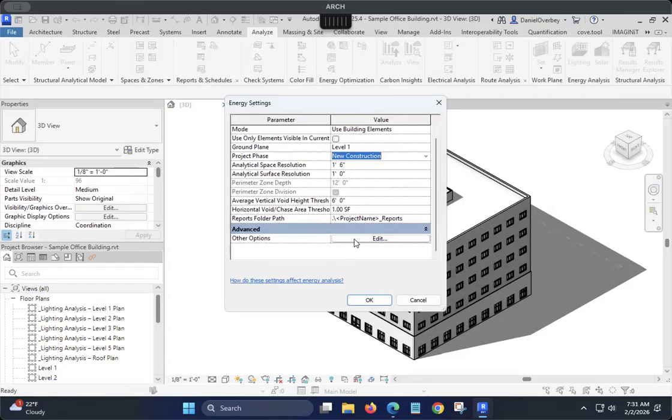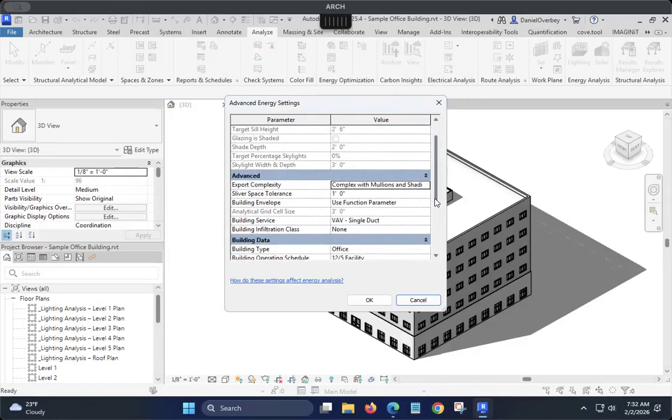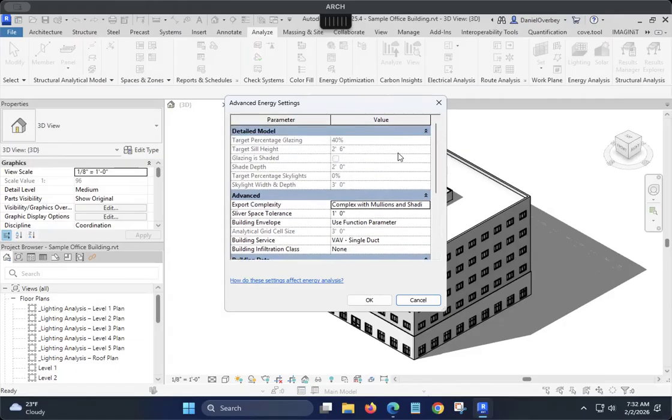But when you go to the advanced options menu here, you're going to see a list of options that are going to actually have a very big impact on the energy use intensity, the energy performance of your project. Notice this first one here. This is shaded out. This information is active when instead of a model that you can see, a Revit model where I have some basic assembly types and it represents a piece of architecture. It has enough information in it that we can start to define what some of the assembly types are, the thermal enclosure, et cetera, et cetera.